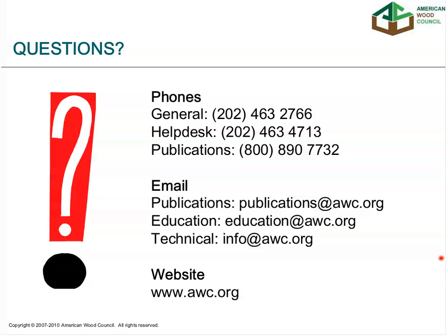Does an exterior application like a trellis get considered as wet, wet-dry, or dry design condition? If it's an exterior application, and when you say trellis, I'm assuming that the wood members that the connections are in are directly exposed to moisture, then those would be considered wet in-service applications. I've seen timber bridges with a trellis along the edge of the timber bridge. Those, in my opinion, would be external or wet service applications.